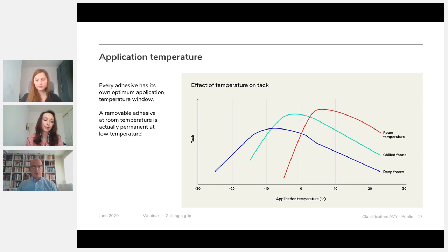So again, even if you have no firm points from an end user on what the final adhesive requirements are, then three points are always very important to consider. One being the minimum application temperature at which the adhesive needs to stick onto the substrate. The second one is the roughness of the substrate itself, and finally the polarity of the substrate.